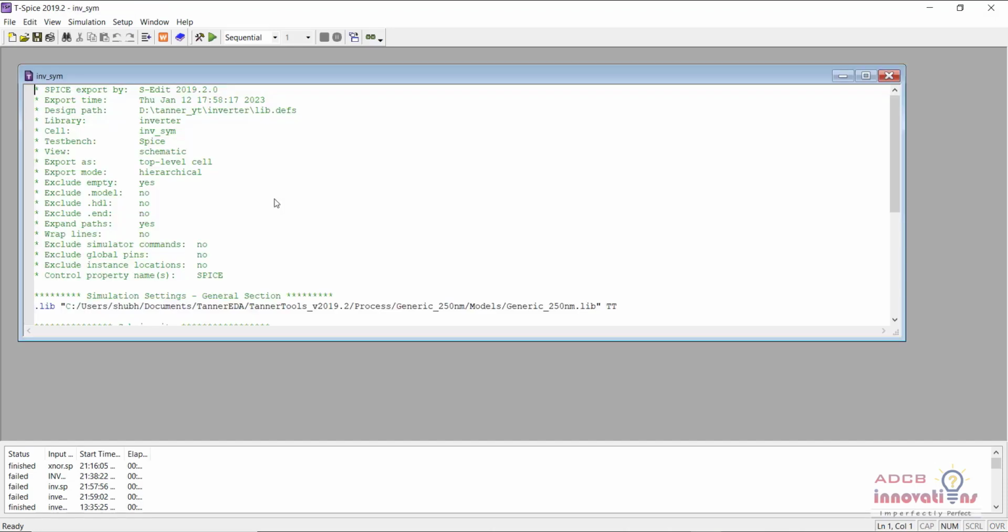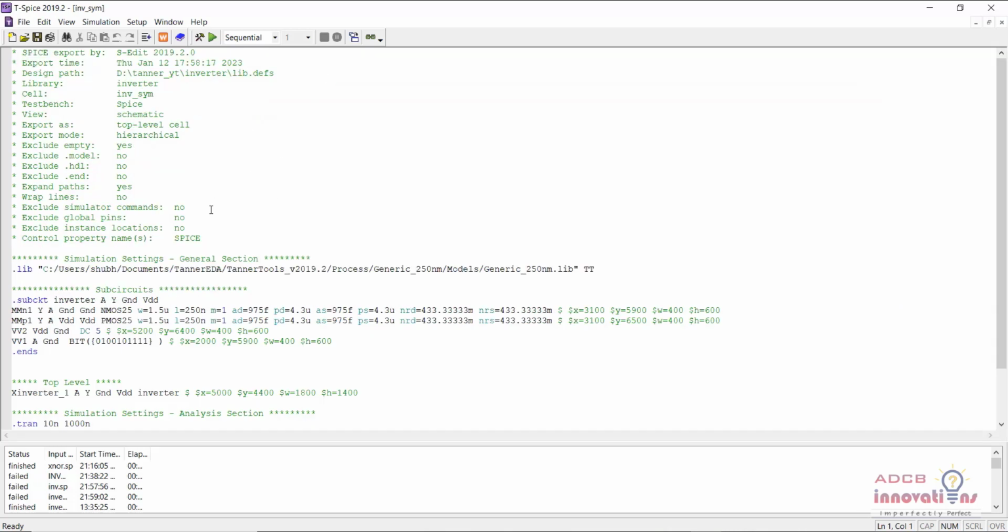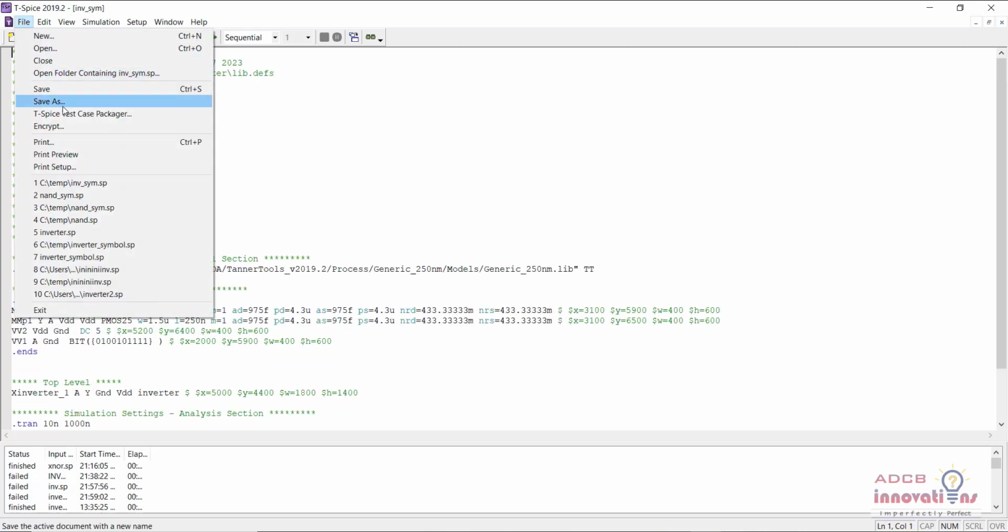Alright, basically at times you can directly publish without creating a tSpice file as well, but this Spice Netlist file can help you recover your layout if somehow you lose it. Okay, so here is our tSpice file. Now you need to remember this subcircuit name, that is .subckt inverter. Just click on File, Save As.